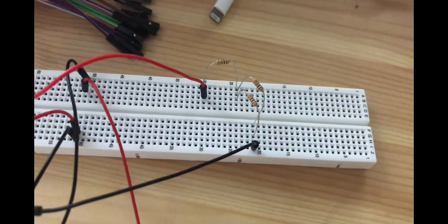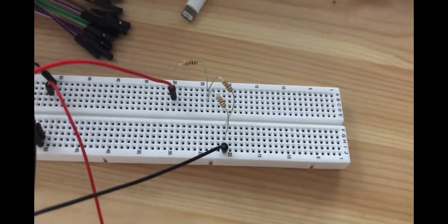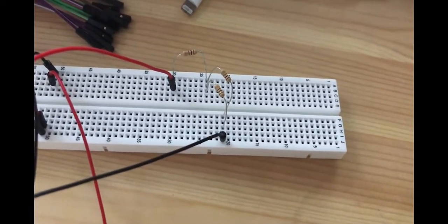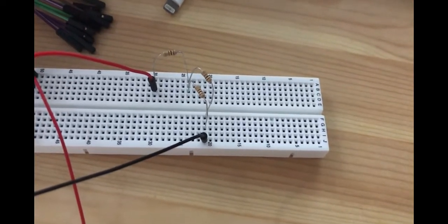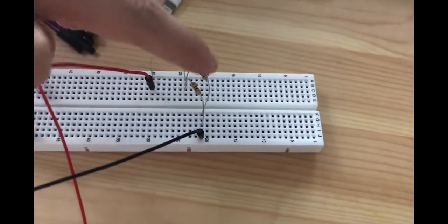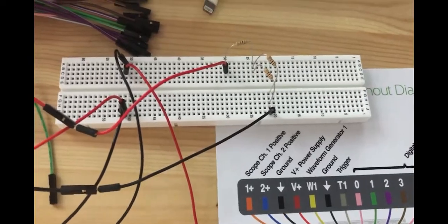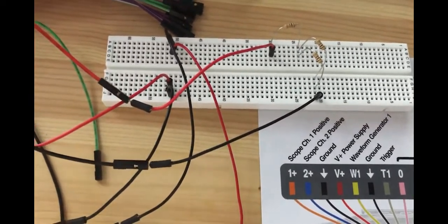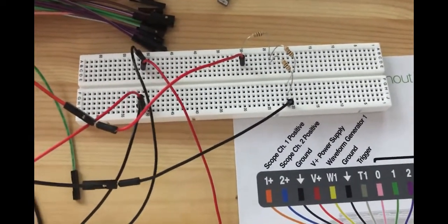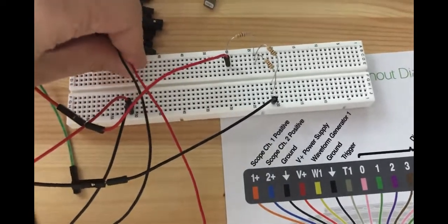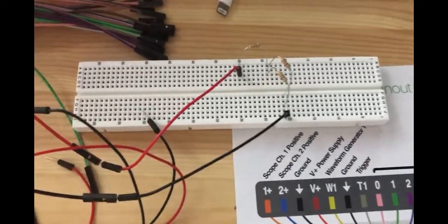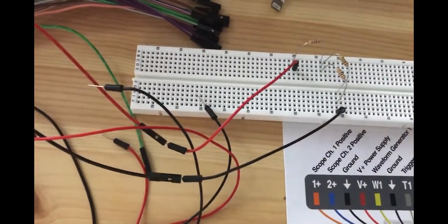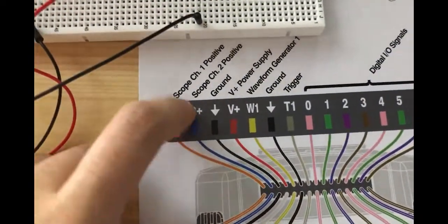And the question is asking you to measure the voltage of R3 with oscilloscope and see the maximum and minimum voltage. R3 is this one. To do the measurement, you also need to connect the oscilloscope wires to your circuit. These are from the previous part. I'm bringing them out, and so the oscilloscope, as you can see here, the positive is the orange one here.